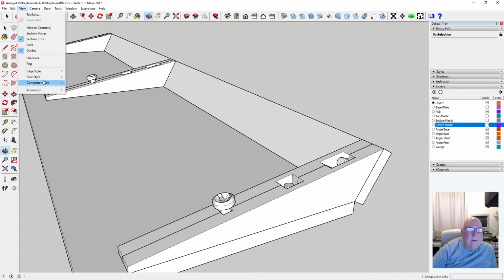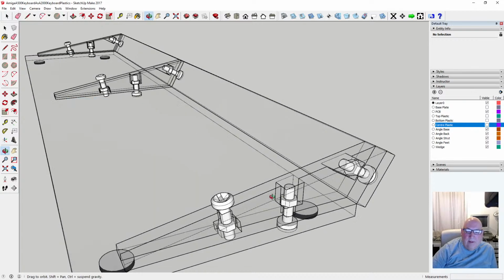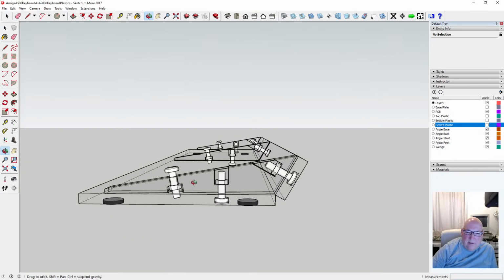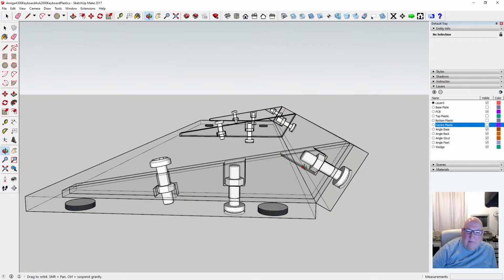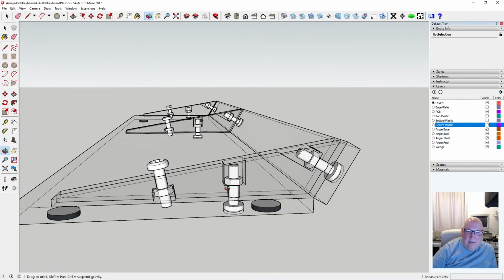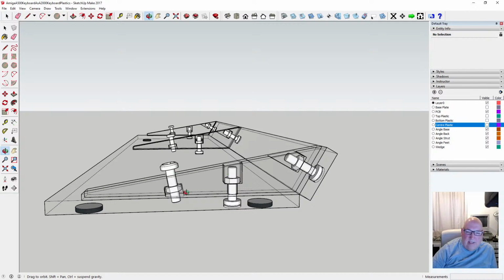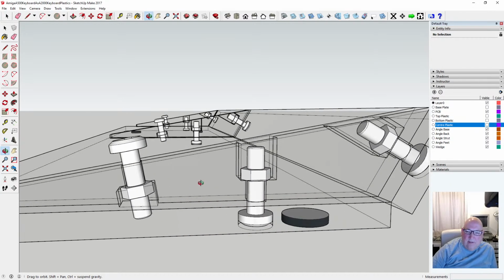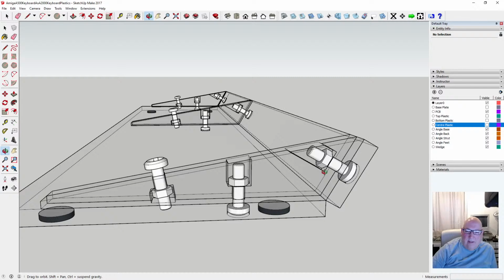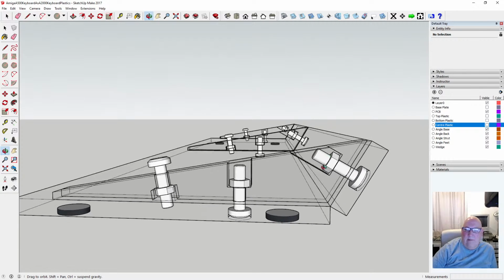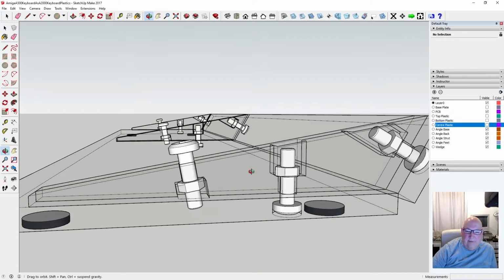Let's view it in normal mode a minute. Let's see where we can put the stitch. So we can put the stitch there. Yeah, if we put them between these two, because that fastens it down, that fastens the back on. And that fastens the base to there, so could just put it in there, in the middle of there, maybe. Yeah, because that's not structural there. Base and lid are structural, that's just a back plate. So we'll put it in there, okay.